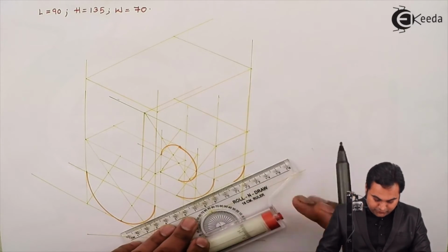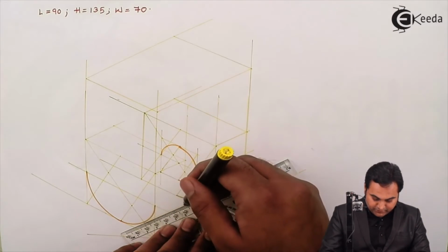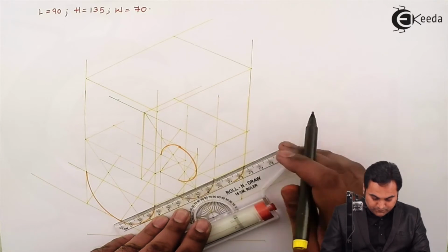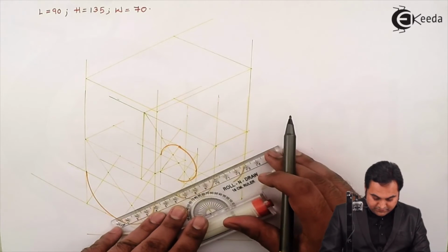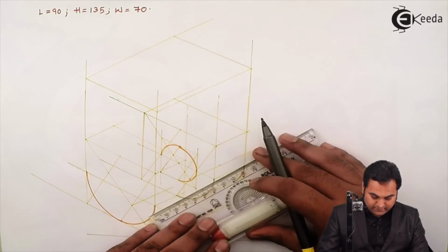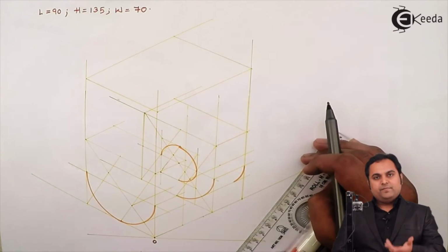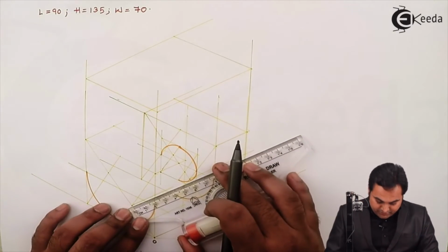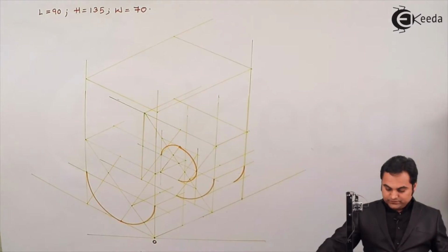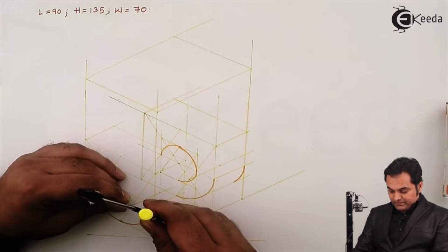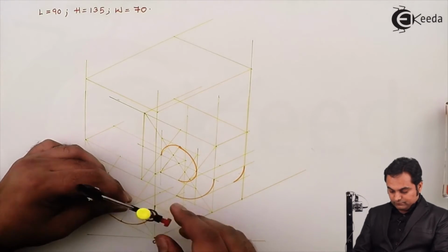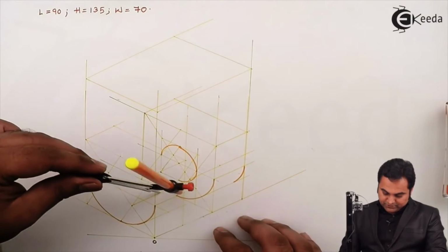here I am taking this point behind where it is cutting the longer diagonal, this point also behind, and next the center which I had used, it will also go back. Since I have to draw 30 mm behind, I'll mark 30 mm distance on this center line, keeping the same radius as taken below. Only the center is going to shift, which is here. I'll draw the semicircular part.